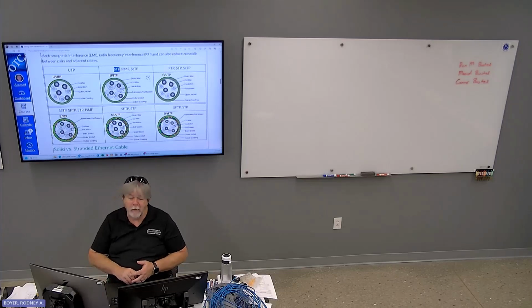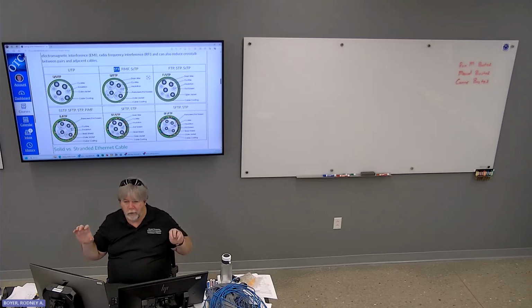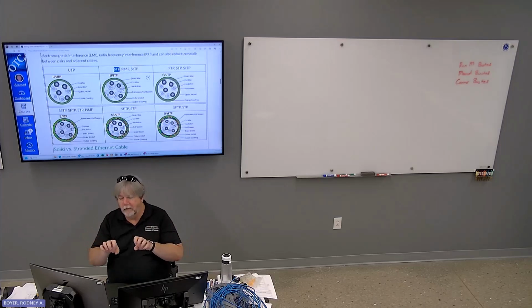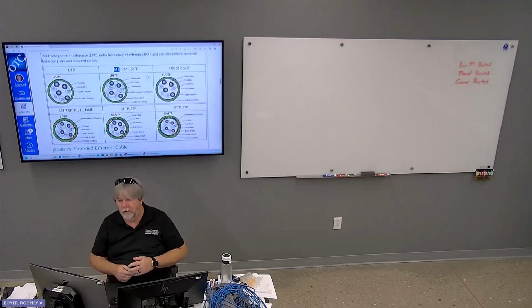With a VFD cable, you want to ground it on both ends because you're trying to create a Faraday cage to keep the noisy signals in the VFD cable from getting to the outside world. It's also transmitting usually AC, right? AC signals. Yeah, going back and forth.